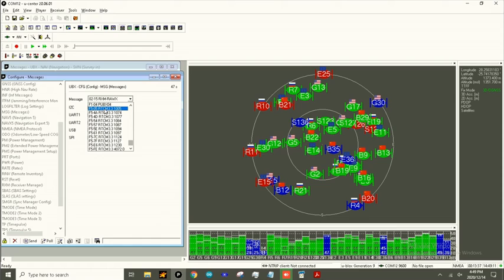And for this particular receiver and the different bands that are currently used, the following messages need to be enabled. The first one is F5-05, and we only need to enable this on the USB interface, which is the interface that we are using. Then the next one is 1077, or F5-4D. All of the messages ending in a 7, I believe, have to do with the new generation of receivers, so we'll enable that one as well.